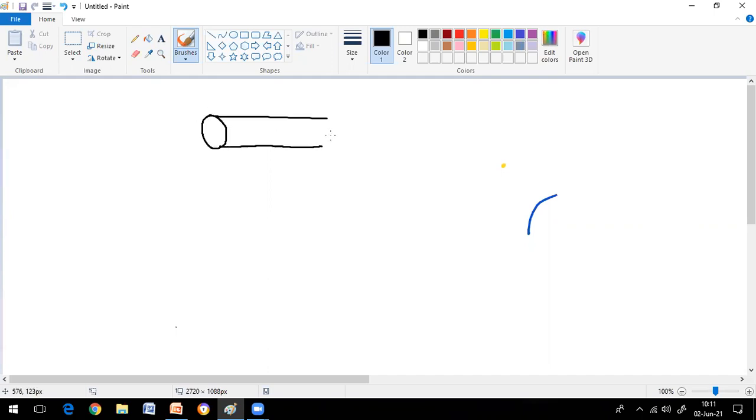See, this is your cylinder with respect to its length. When the internal pressure acts, it acts on the circular circumference, I mean on the cylinder. Let us take section XX here. If you cut the section, you can see it like this. The pressure will be acting on its circumference, which is going to burst your cylinder in this way. This is your pressure, right?